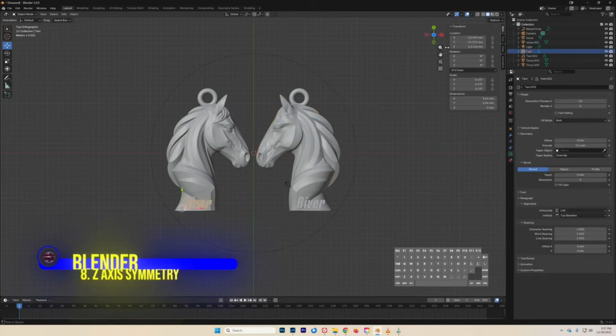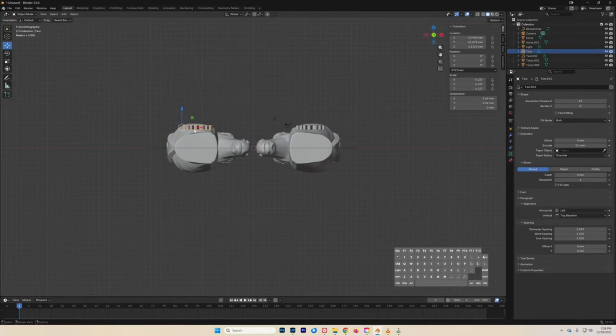And then our text. Now here's where things do get important. So I'm going to flip my view on my text really quick. And the position of our text in this particular instance, the thing that is the highest in the z-axis is going to end up with the brightest level and will engrave at the surface of the coin. If I put this way up here, that's the top surface of the coin, it's going to start engraving this much deeper, which I don't want. But if I put it down here, this will be the highest position, and then my text will be lower.